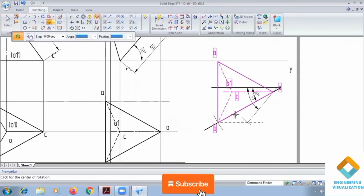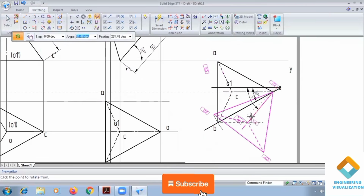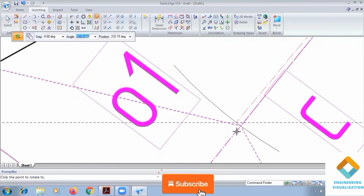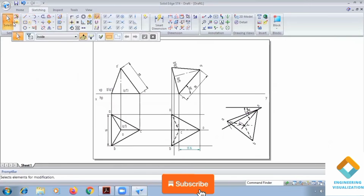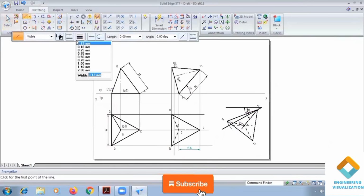So using the move command we have copied. Take the reference point of OC and place it on the angle line here. Place it pinpoint. You can zoom in when you're placing it. Okay, so now draw the projection lines to complete the final position here.